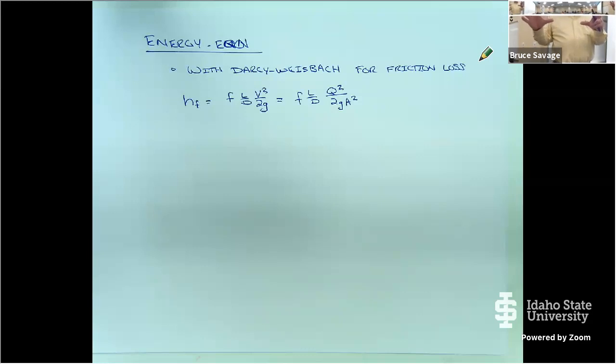No one to my knowledge has proven this, but people hypothesized that large diameter pipes, because they are so big, a large area compared to a relatively small surface that the flow is going through, also somehow set those vortices up on their own and bring the flow down. Ted's saying, if I would have known this, I could have put in a 9 foot pipe rather than an 11 foot pipe. I would have had a little more loss, but the $500,000 that he put out on the larger pipe could have been saved. Okay, so it's an interesting phenomenon.